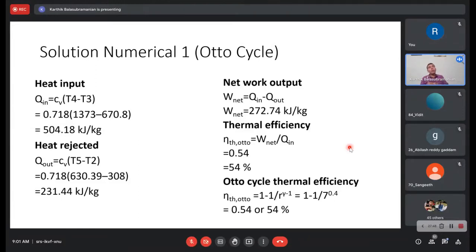You can just calculate it. Consider the calorific value of the fuel. If you find out what mass of fuel is coming into the cylinder, and the amount of energy that is released, one third of it is just getting dissipated through the walls. So the cylinder walls can completely warp, and many components can melt if you don't have a proper cooling system in place. We'll discuss that while discussing the cooling system. But since the term efficiency came up, I wanted to bring it into perspective: there's always a limitation on the amount of heat that can be utilized for useful work, right?